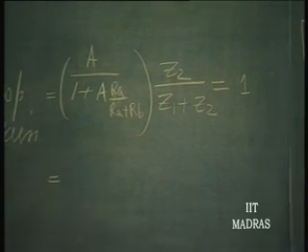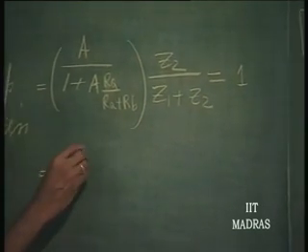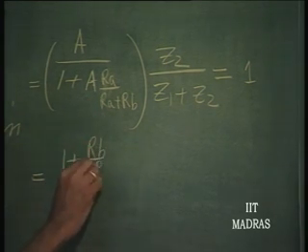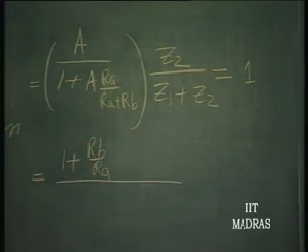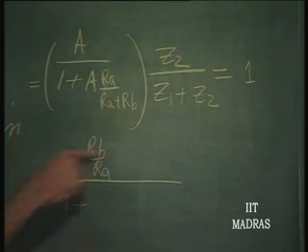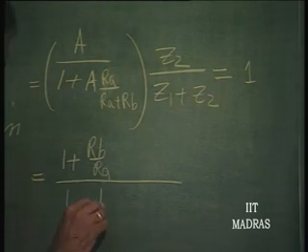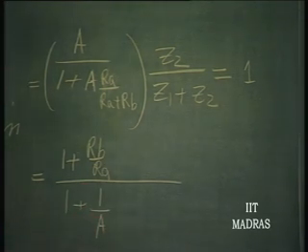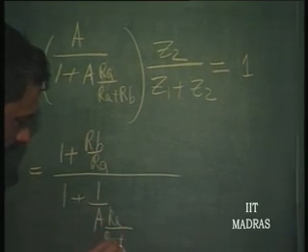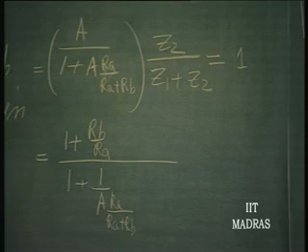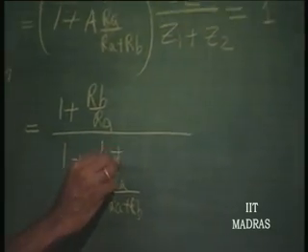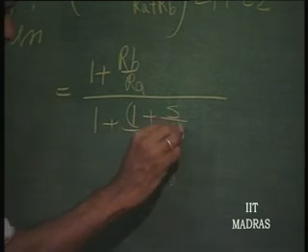So, this is equal to, we will divide, this gets 1 plus R_B by R_A, which is actually the gain, divided by 1 plus, I am dividing by A beta throughout. So, 1 over beta comes here, 1 plus 1 over A into beta, that is R_A by R_A plus R_B, which is written as A naught into 1 plus s by omega d.